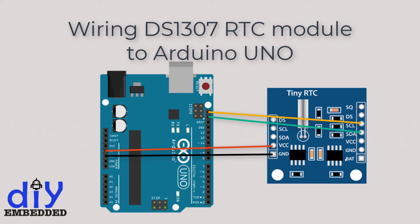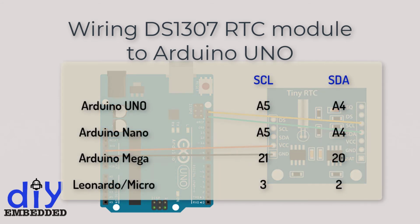Please note that each Arduino board has different I2C pins, which should be connected accordingly. On the Arduino boards with the R3 layout, the SDA, data line, and SCL, clock line, are on the pin headers, close to the analog reference pin. They are also known as A5, SCL, and A4, SDA.